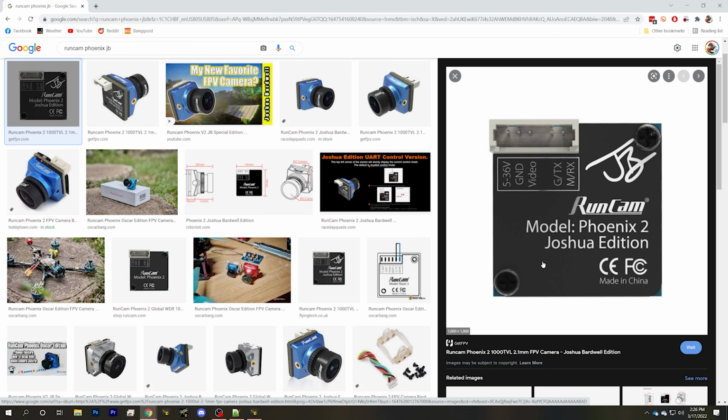Those cameras will often have a TX and an RX line that can be used to remote control the camera. On analog cameras, you can use your joystick to configure the camera options like brightness, contrast, and so forth, instead of plugging a joystick into the camera. For the Runcam split and so forth, you can actually set up switches to start and stop recording, which some people like. I've got a video more about how to set that up, but the takeaway is that if you look at the back of your camera and you see a TX and an RX wire, you can wire that up to a UART on your flight controller, and then you can remote control the camera and configure it and so forth.